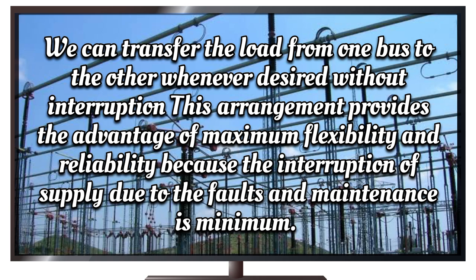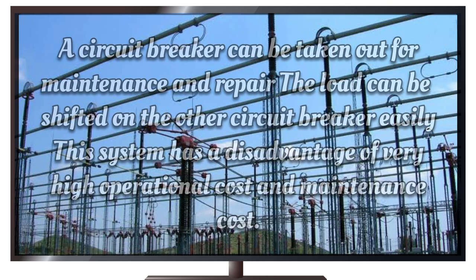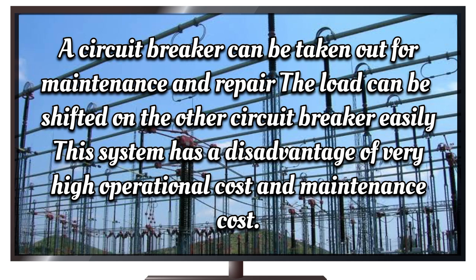This arrangement provides the advantage of maximum flexibility and reliability because the interruption of supply due to faults and maintenance is minimum. A circuit breaker can be taken out for maintenance and repair. The load can be shifted to the other circuit breaker easily. This system has the disadvantage of very high operational cost and maintenance cost.